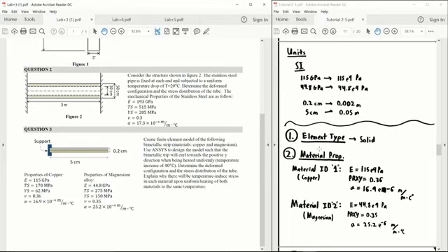In this ANSYS tutorial video, we will be looking at Lab 3, question number 3. Before we get started, we first have to determine which units we're going to use throughout this question. Looking at our example, our best option would be to use the SI column of the table of consistent units, converting all of our gigapascal values into pascals and all of our centimeter distances into meters.